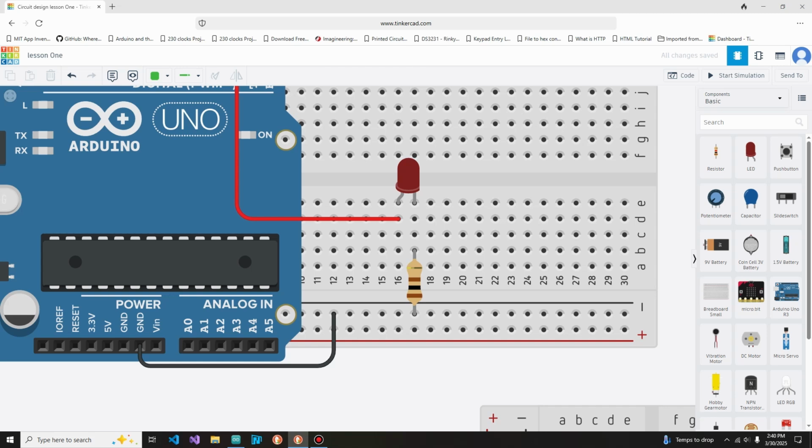The thing that you really need to pay attention to is the size of the resistor. The size of the resistor dictates how much power it can handle. And I have two examples I'll show when I get my feed going for the Arduino. I have a 1/8 watt resistor and a 1/4 watt resistor. So the size dictates the amount of power it can handle. The bigger it is, the more that you can work with. You have ones that can go up to 1/2 watt, 1 watt, 5 watt. I mean, they start getting really big.